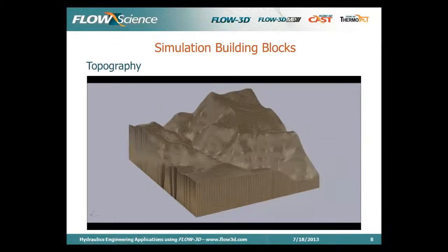And since a foot scale grid size is not uncommon on downscale problems, at this point I would suggest you get the best topographical data you can, because computers have basically taken the lead for now, at least on these scales. So this is the topography we'll use today.